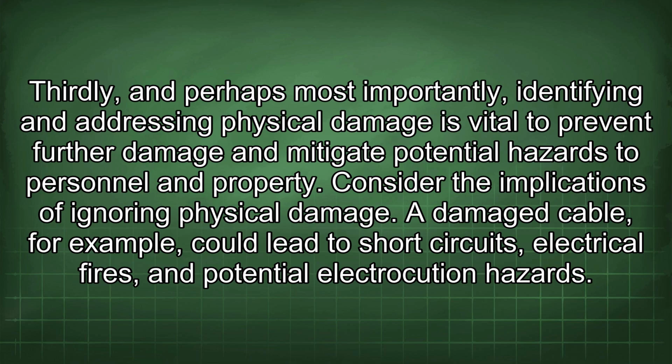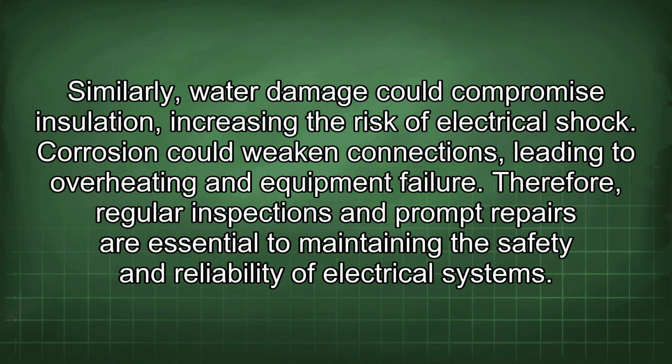A damaged cable, for example, could lead to short circuits, electrical fires, and potential electrocution hazards. Similarly, water damage could compromise insulation, increasing the risk of electrical shock. Corrosion could weaken connections, leading to overheating and equipment failure. Therefore, regular inspections and prompt repairs are essential to maintaining the safety and reliability of electrical systems.